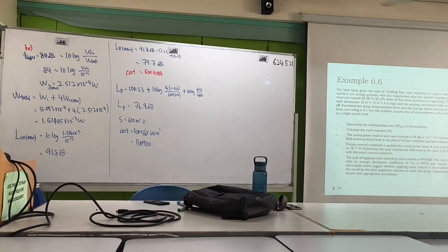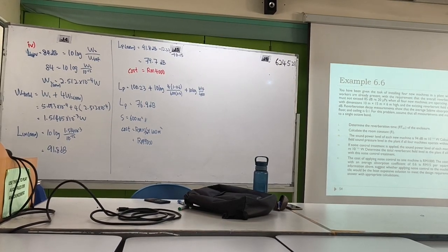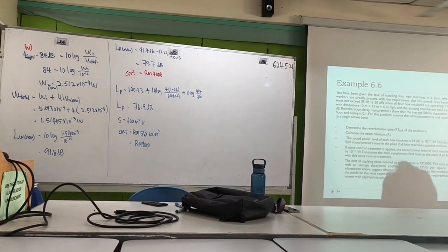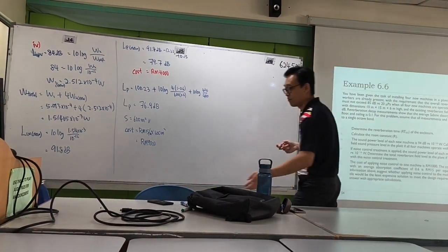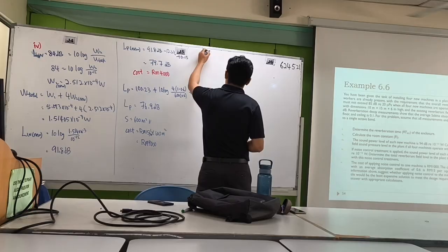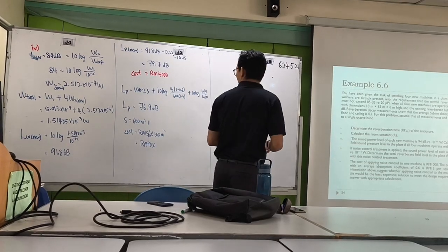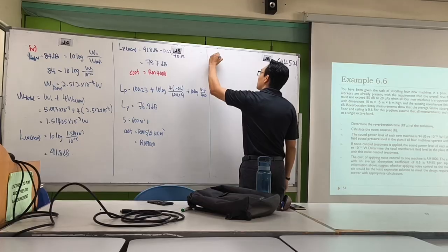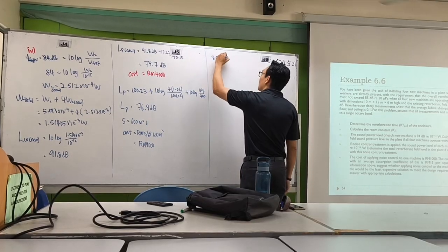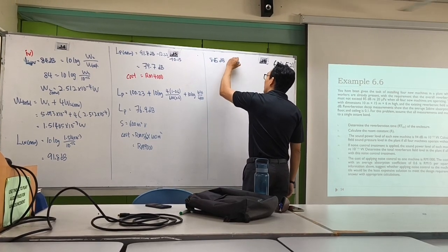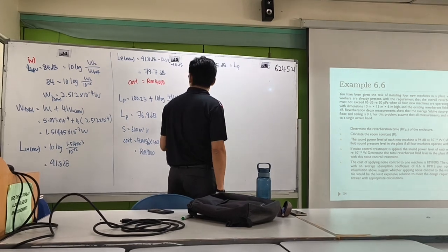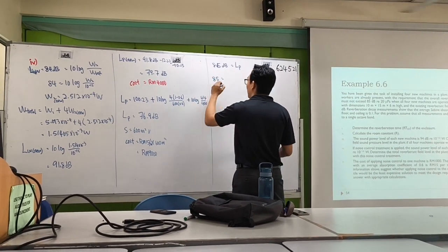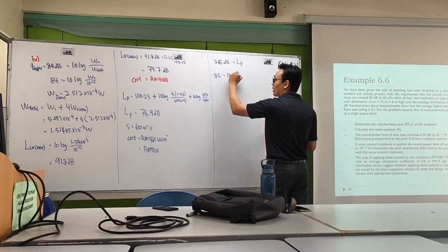Yeah, correct. You don't need to cover all the surfaces. You can only cover the wall or ceiling. Okay, so now we need to calculate how many surfaces are needed. Based on the requirement, 85 dB, this is our LP requirement. So I apply the same equation. 85. The sound power is 100.